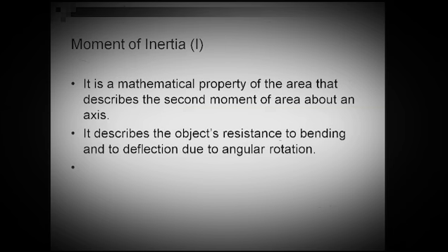So if I were to give you again the same objects that we were comparing, the rectangular one, 8 by 4, and the one on the flat, 8 and 4, which one would have a bigger I? Quickly you said this would have a bigger I value than the one on the left. Now, I ask you the same question in a different way: which one is better suited to resist bending and deflection?